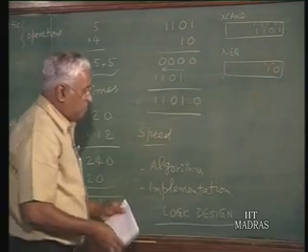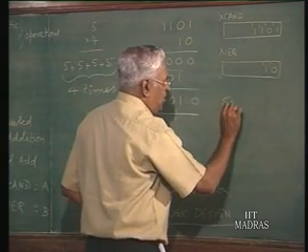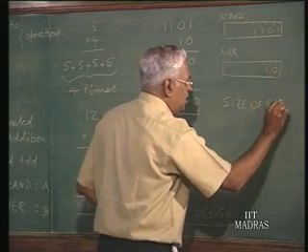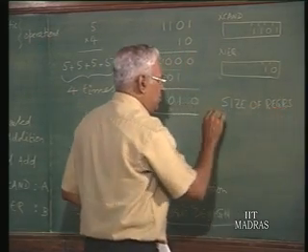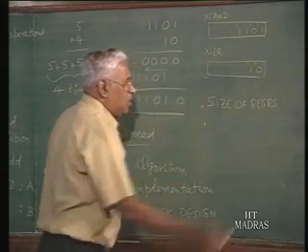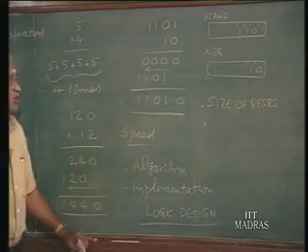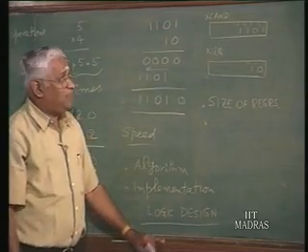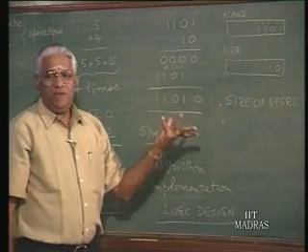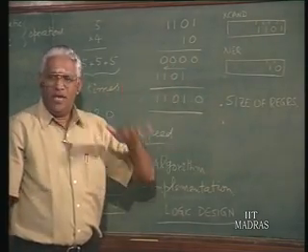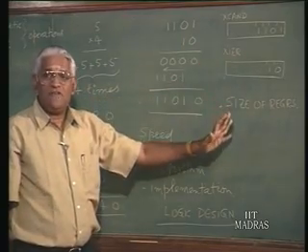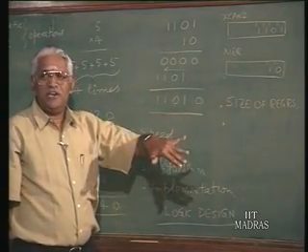The size of registers depends on the problem, but we have to necessarily handle only an 8-bit number, meaning maximum 8-bit multiplicand and 8-bit multiplier, but the result will be 16-bit, which will have to be accommodated in 2 registers.